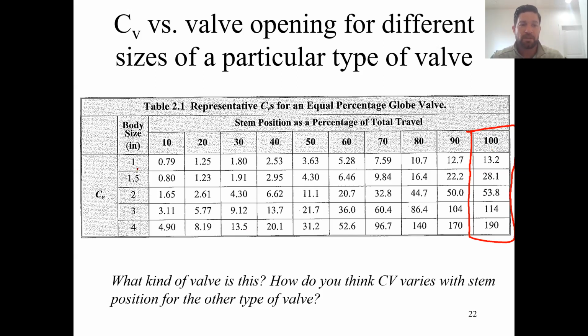So for example, if you decided that you need a linear valve, and it needs to accommodate a maximum flow based on the pressure drop that has a CV of, let's say, 40, these would be too small. Maybe you would look at potentially this one right here. So for linear valves, we just use CV max based on 100% open.